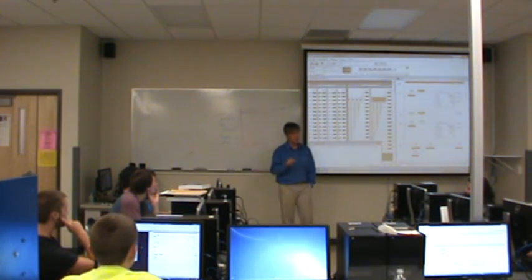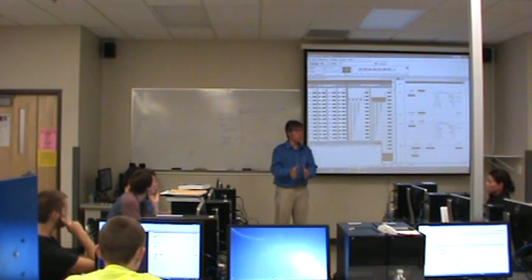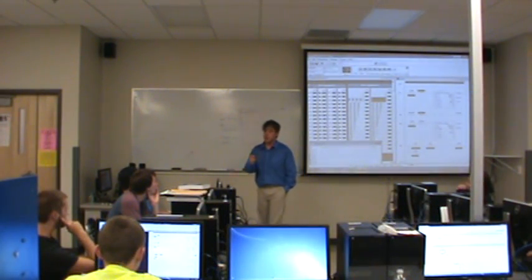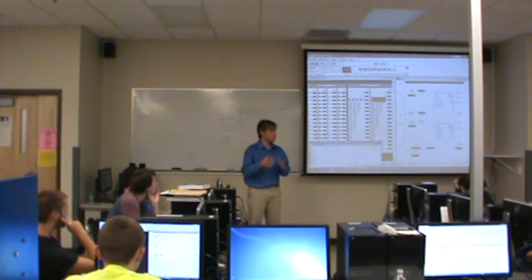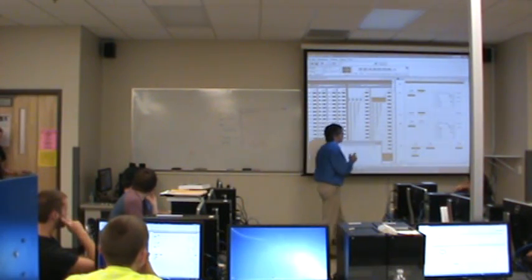But a lot of times, you can't just base it on time. You can't just say, once so many seconds have elapsed, I'm going to assume there's another bag in place that I can fill with candy. Okay, you can't do that. You have to sense that the bag is actually in position. There's probably a lot of other requirements before you try to fill the bag with candy. So that's where the sequence compare instruction comes in.